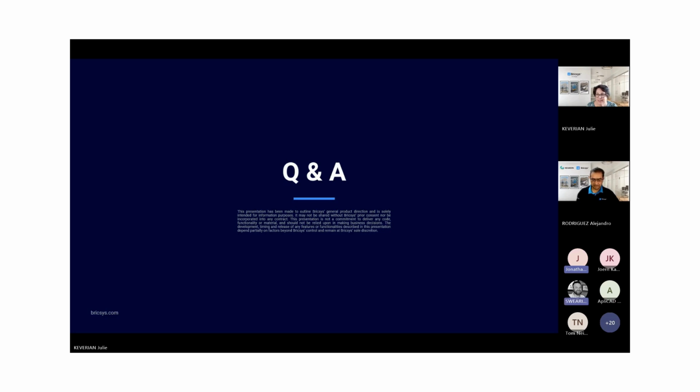I think it's closed. But basically I was just going to ask about the option in BricsCAD for point symbols. We can use them for manholes, water valves, that kind of thing, and also for point labels. What we can do is turn off the point number and the point description and add a suffix or a prefix. So we have a point label that automatically says like TC 100.00 and so forth.